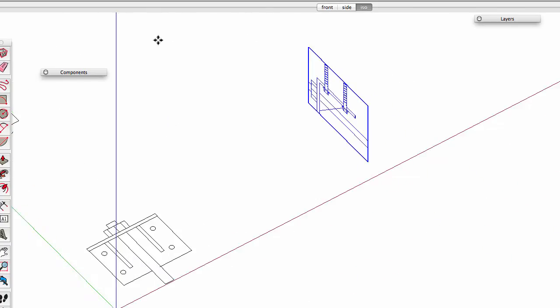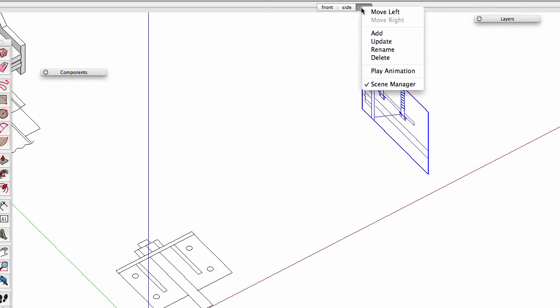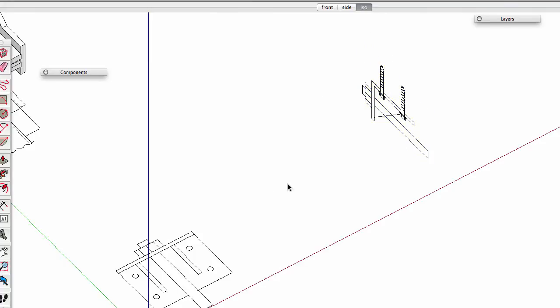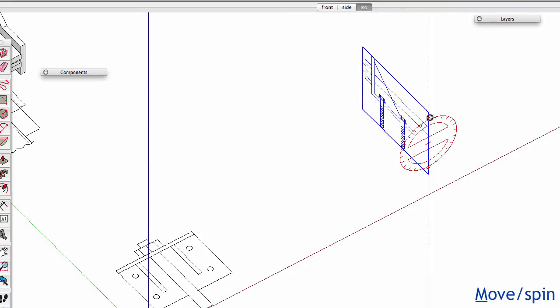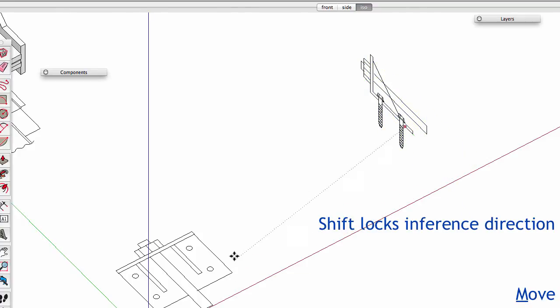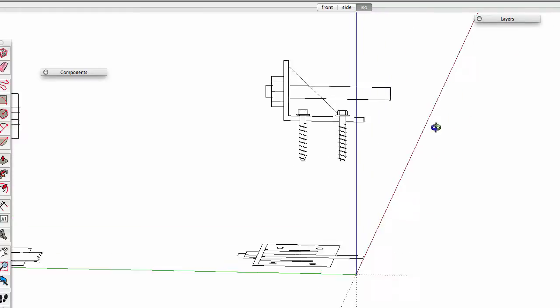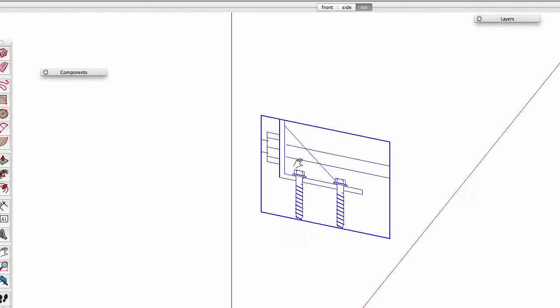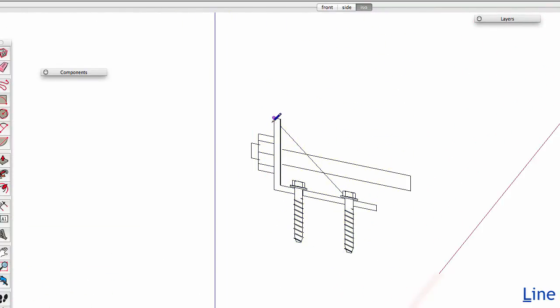And then ISO view will update the ISO view, and we're ready to roll. Except this bracket should be seen from above. So let's spin that. You want to make sure you get your 2D placed to match each other. And then we'll have the end of this bracket, bent plate, line up with that one. Okay, now we're good. Let's start modeling. L, and we'll draw in the bent plate.